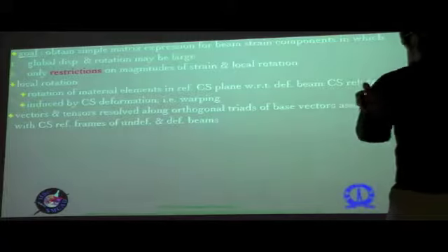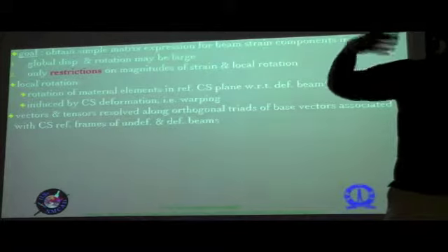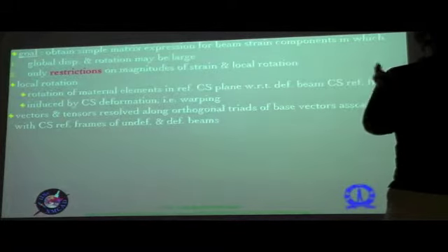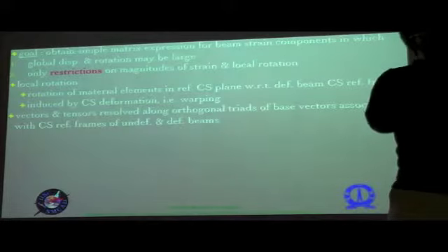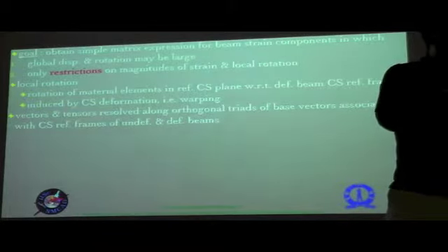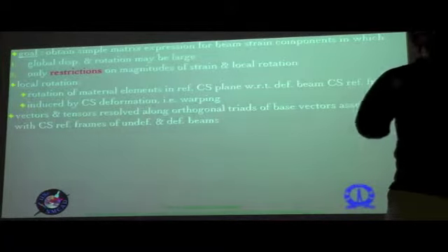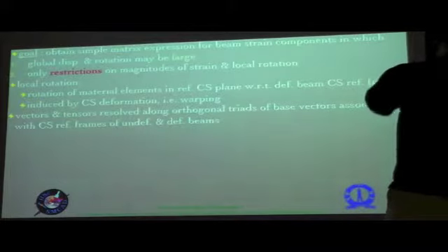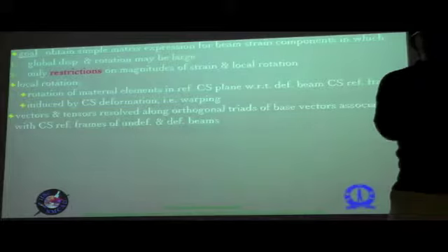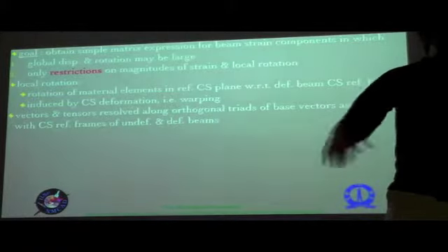But within hyperelastic materials, there is a class of materials which can take strains only up to the order of 20%, 30%. Okay. In such situations, we can still deal with epsilon as a small parameter compared to unity, because 0.2 or 0.3 is small compared to unity. But the interrelation between the small parameters changes, because remember there are multiple small parameters here. One is the strain, the others are the geometric small parameters like the thickness to width ratio, width to length ratio, etc. Now the relative orders of magnitude of these small parameters will change for hyperelastic materials, and therefore the theory that you derive and the results of the theory will also change.